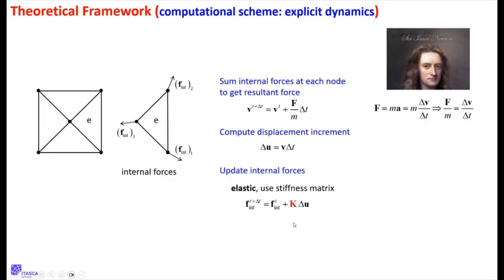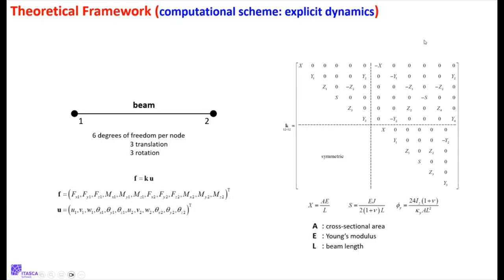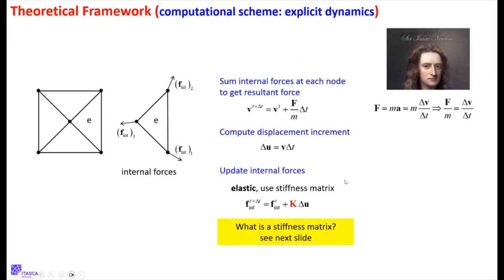And so what is a stiffness matrix? Basically it's a closed form expression based on, here we go, area, rotational inertia, all kinds of stuff, area, Young's modulus. This is an example. This would be a beam finite element. In our case, we have a shell finite element. We don't got to go into any more detail. The key thing is there's a known analytical solution that lets you build up this sucker here. And this is what I had already done ages ago in FLAC 3D. And so there's a known analytical function for this. So I implemented all that and we could solve all these elastic problems.